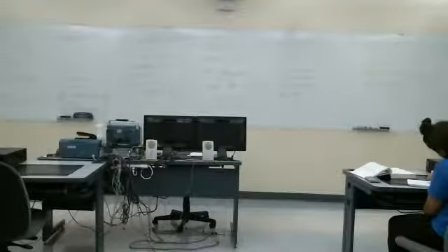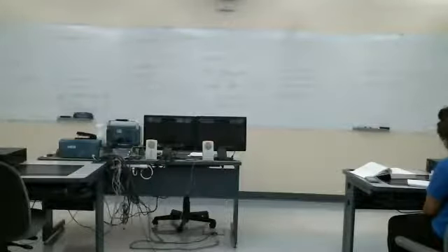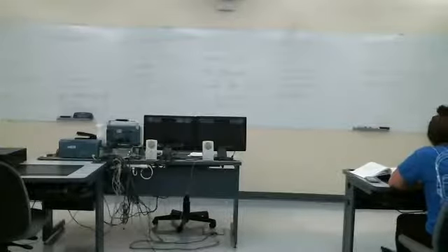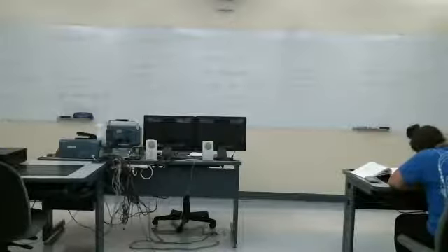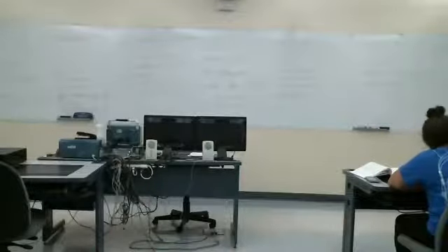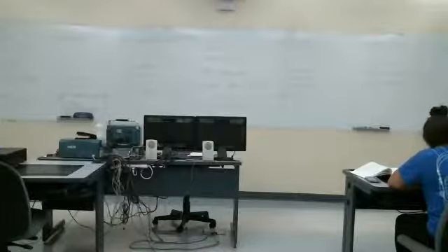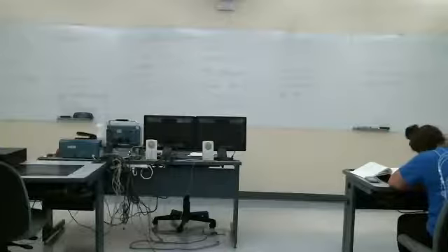Everyone okay with that? My system just multiplies my input by t. My input now is a unit step. So for all t less than 0, the unit step is 0, so that product is 0. For t greater than 0, my unit step is 1, so I'm just multiplying it by t. Now, what does y of t minus delta look like? Well, we know what that looks like, right? It's just this thing shifted to the right by delta. That's what the delayed output would look like. This is y of t minus delta, taking my original output and delaying it by delta.